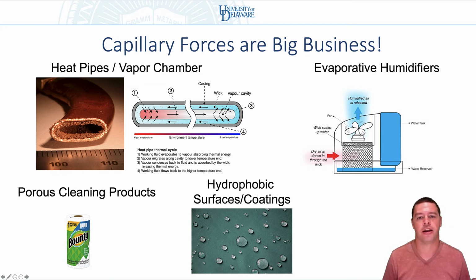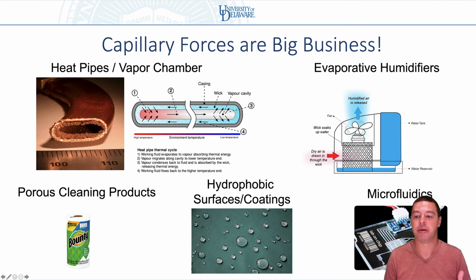I didn't go into a lot of detail, but it turns out if you can get a droplet to sit on basically a coating of air, so often what people will do is create Teflon pillars and make sure there are spots where air touches the droplet underneath. That'll tend to make the water want to bunch up into balls or droplets a lot more. So making surfaces that are both coated in hydrophobic solids, but also have some pore space to increase that effect, is big business.